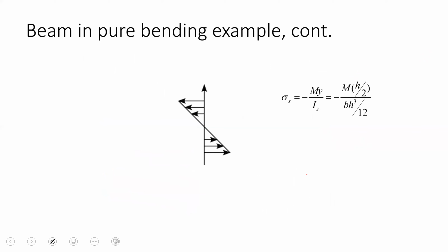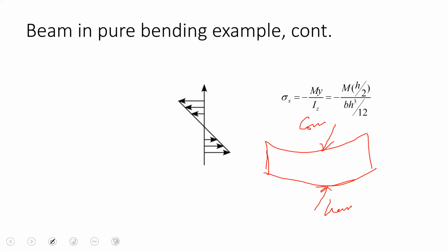And obviously whenever the bending is there, both compressive stresses and tensile stresses are there. Whenever you get this sort of bending, that is a positive bending, this surface will be under compression and this surface will be in tension. But at this surface and at this surface, these normal stresses sigma will be maximum.